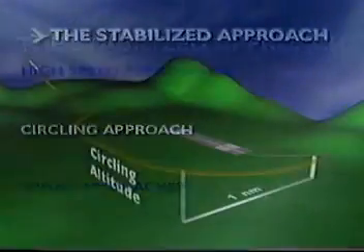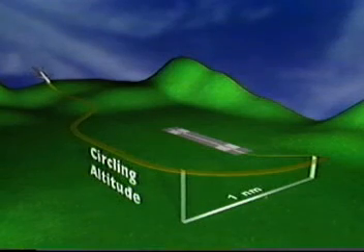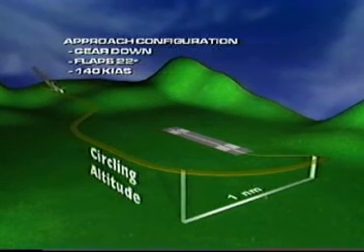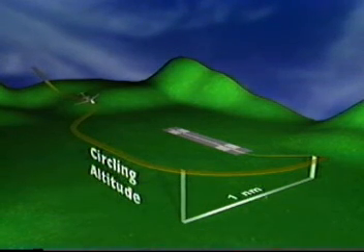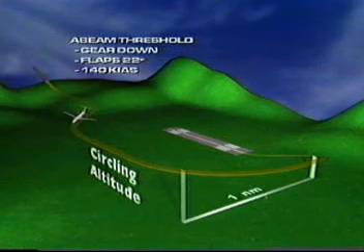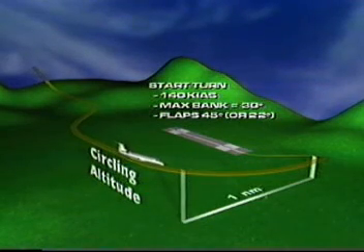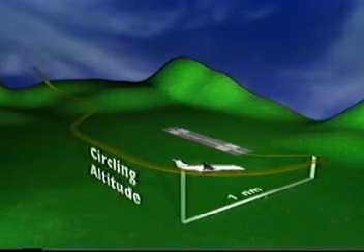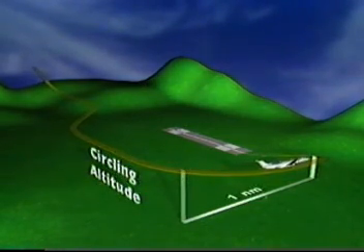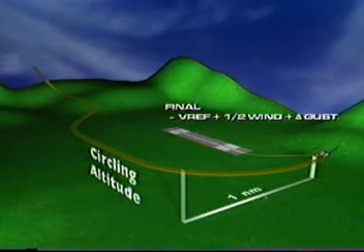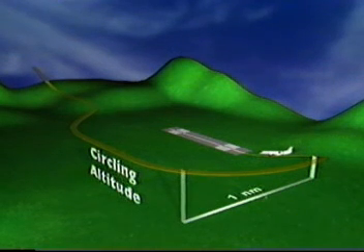Circling approach. Circling approaches are very demanding. They're often very tight maneuvers that may end up in very short finals at the wrong height and wrong speed, that can induce the pilot to use power-off, steep paths towards the runway. And to complicate the matter further, sometimes the runway is at the side opposite to the flying pilot, and he only sees the runway when turning into final, when it may be too late to make corrections.